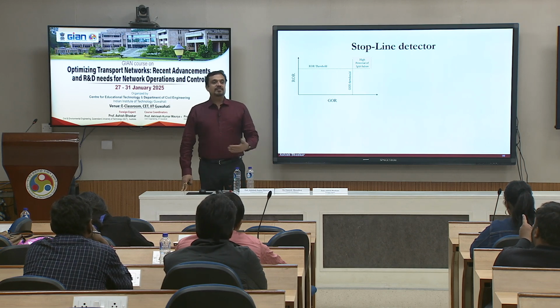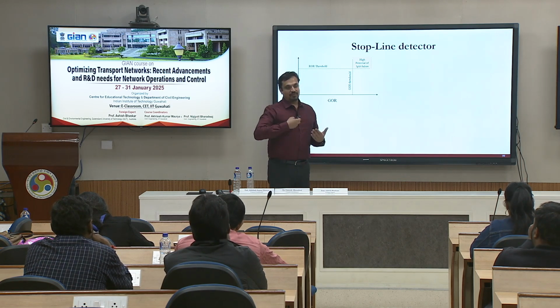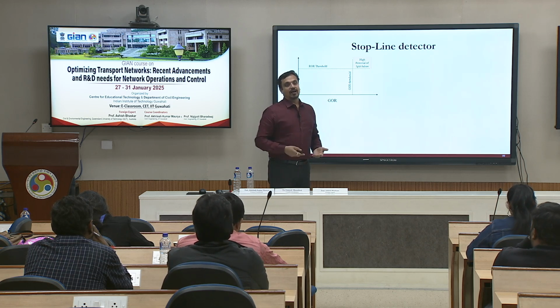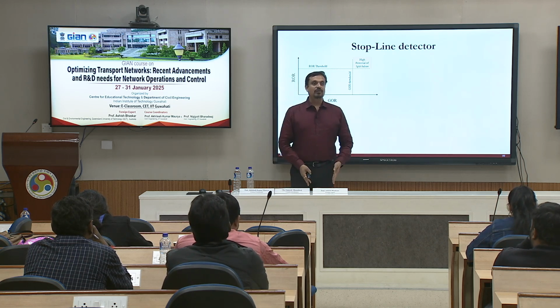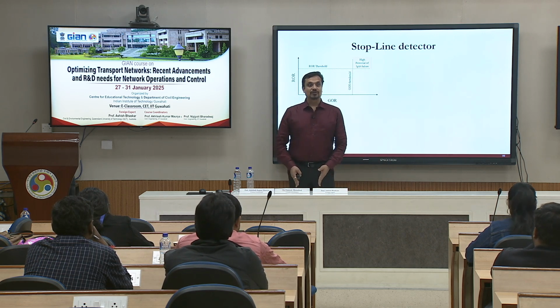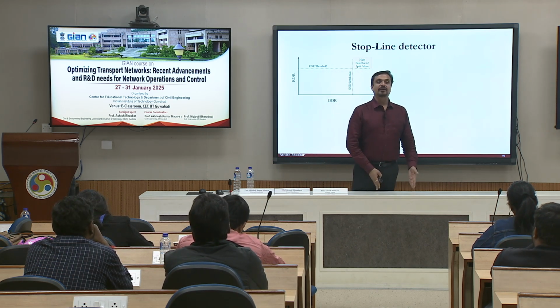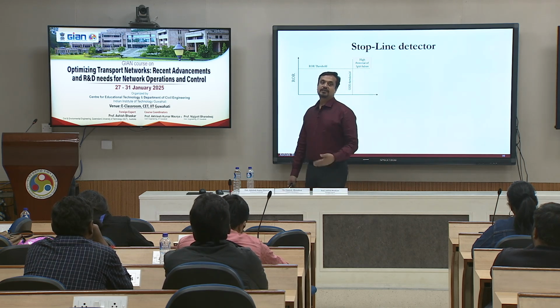Maybe around 4 to 5 seconds would be right, because after 5 seconds, if somebody else is arriving, it can be because the traffic has to come to the intersection, right. We define the split failure when you have to stop twice, not once. If you are stopping for more than one red light, then it's a failure.